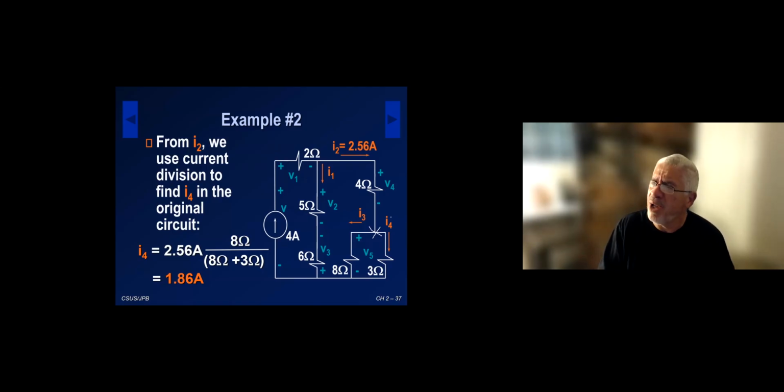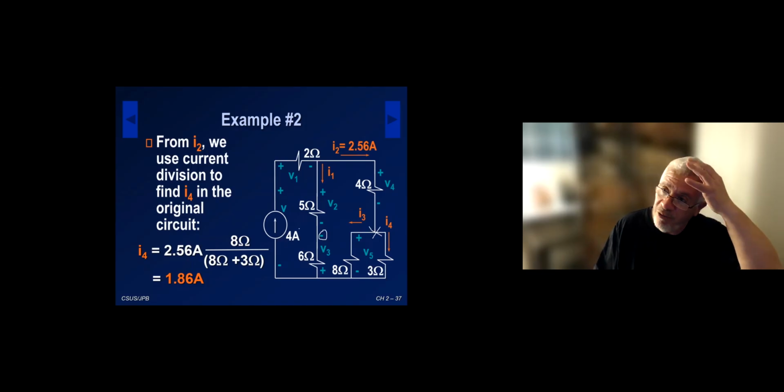So I'm actually just going to calculate voltage here. The reason I'm going to do that is because I want to show you V3, even though I don't follow the passive sign convention. The current I1 is entering the negative terminal of V3, but we can still calculate the voltage. Aside from that, I also need the voltage V across the 4 amp source, and there is no Ohm's law for sources.